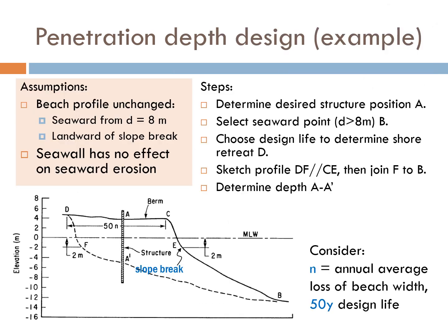On this slide, we are going to discuss briefly the design of penetration depth for a seawall. First and foremost, for the segment of the beach considered, typically it is assumed that the beach profile will be unchanged seaward at a water depth of 8 meters and above.